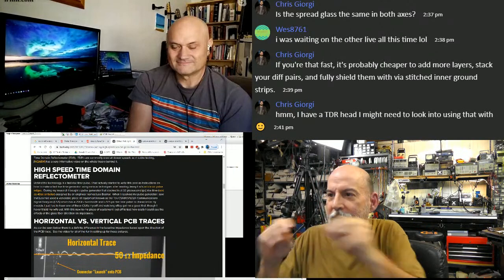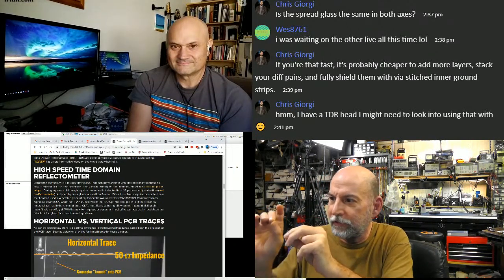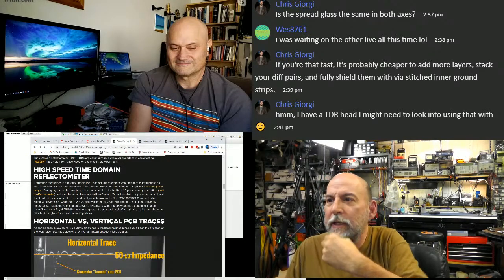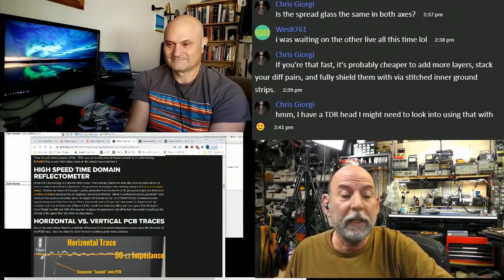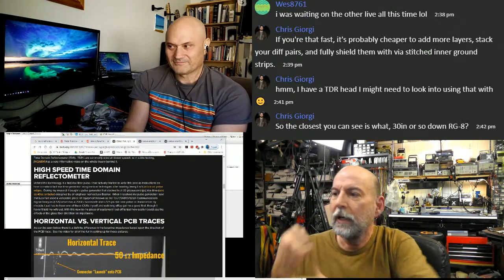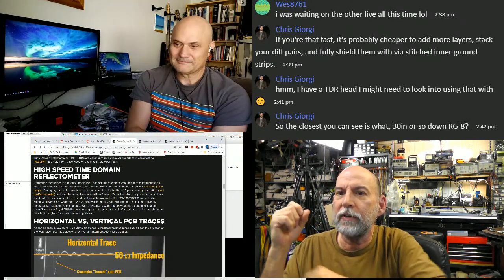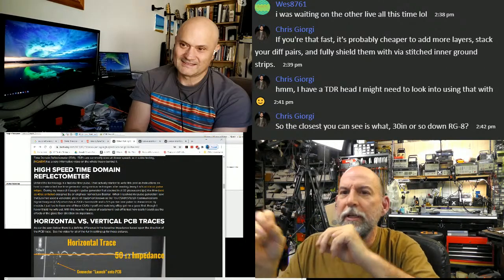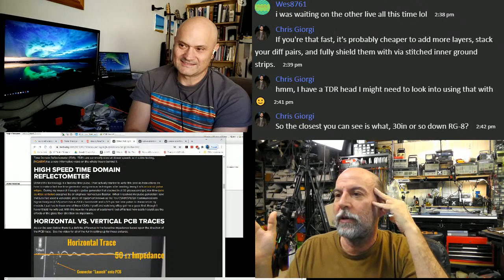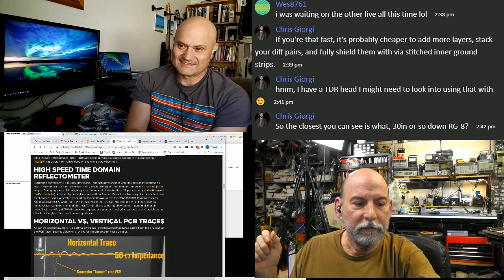The only way they could do it is every part is part of the circuit, even if it's just a wire. And there's only like 5 parts, and there's no ESD protection. This is the one thing, when I use that piece of equipment, I'll actually put on a strap, because if I blow it up, there's no ESD protection that'll go 50 gigahertz, at least back then. So there's no protection on these things.